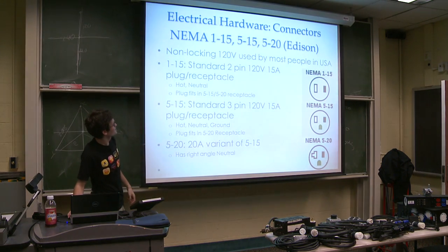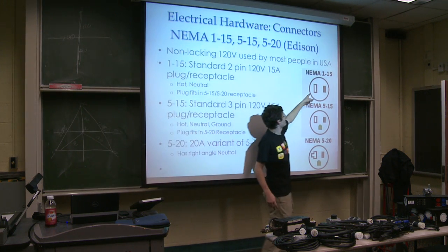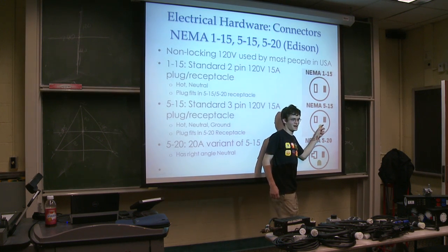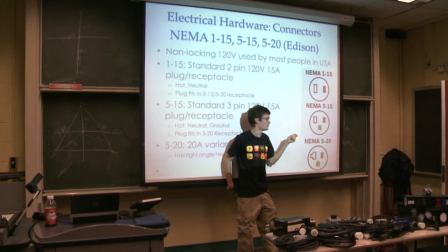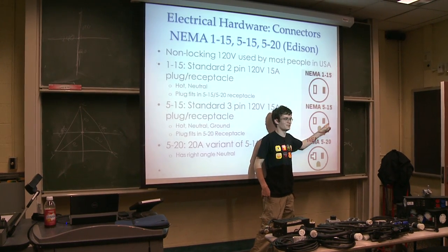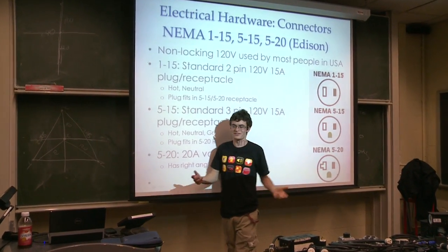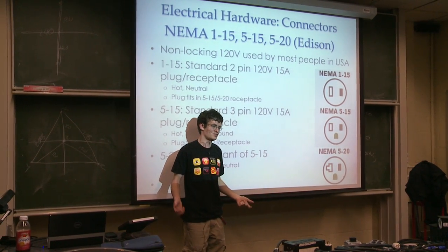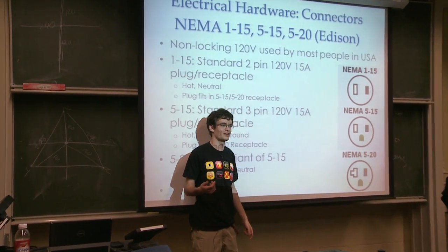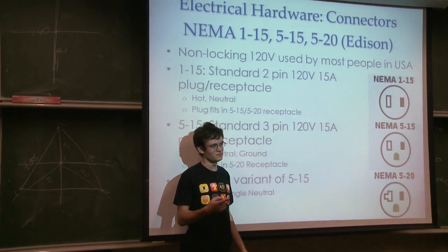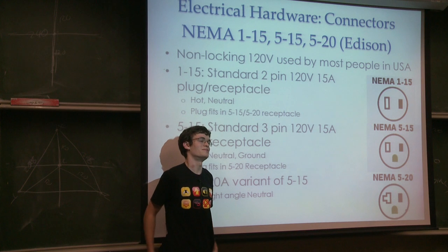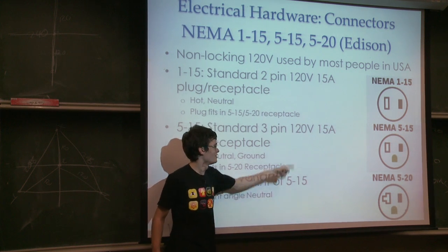Okay. Excellent. So if you look at the diagram, you'll notice that the receptacle on this side is slightly wider than the slot on this side. This is to polarize the connector and prevent you from plugging the hot into the neutral and the neutral into the hot. Some devices are wired in such a way that that could be bad. Lamps usually don't care, so you probably won't see a grounded polarized plug on a lamp, but you do? Okay. Because you always switch the hot. Okay, yeah, anything with a switch, you want to have the hot go in.